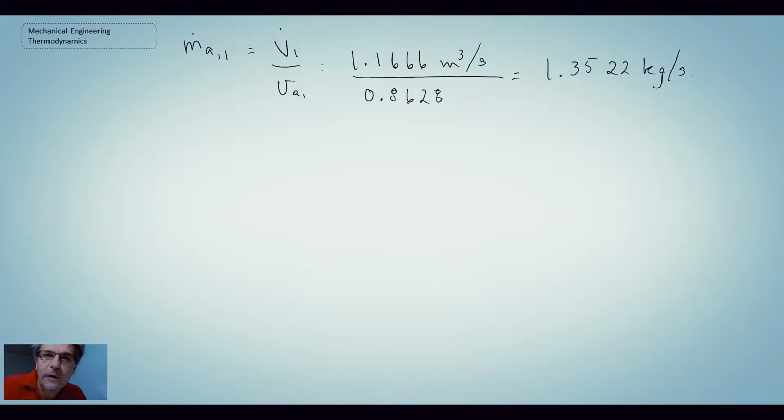So we're continuing on with our example problem, looking at an air conditioning application that has humidification as well as a heating section. So we have heating and humidification, and we have wet steam coming in. At the end of the last segment, we were able to compute the mass flow rate of dry air. So what we're now going to do is look at an air balance.